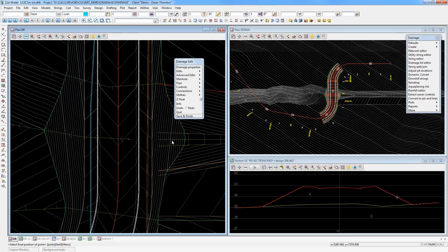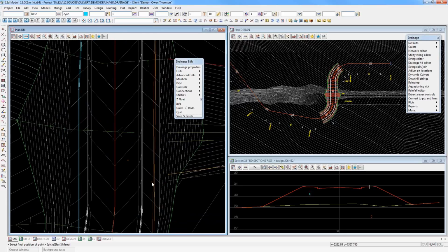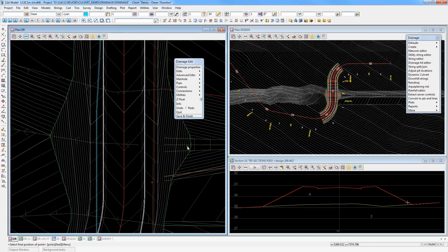In most cases, that's the way they build culverts these days. They certainly try to avoid building skew ones if they can, because they're more complicated and more expensive. But if your incoming swale wasn't perfectly perpendicular, you can still make your culvert perpendicular to your road if you know what you're doing with your snaps commands.